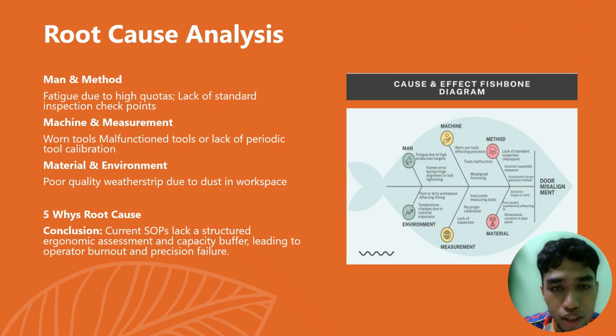For the root cause analysis, the analysis was conducted using the 5M approach and the 5 Whys technique. Several causes were identified. For man and method, there is fatigue due to high production targets, and maybe a lack of proper inspection checkpoint after the operator installs the door parts.